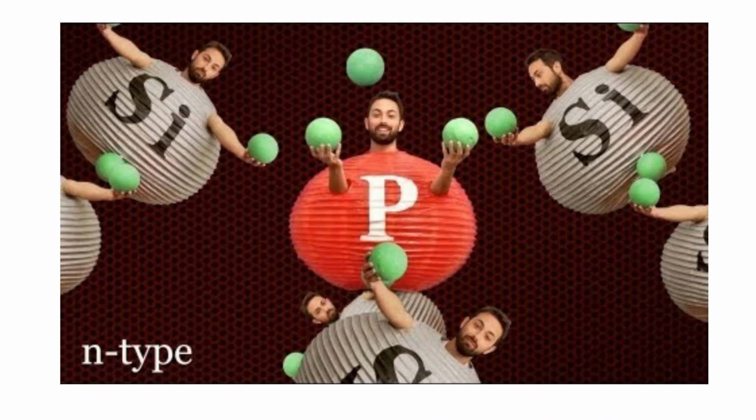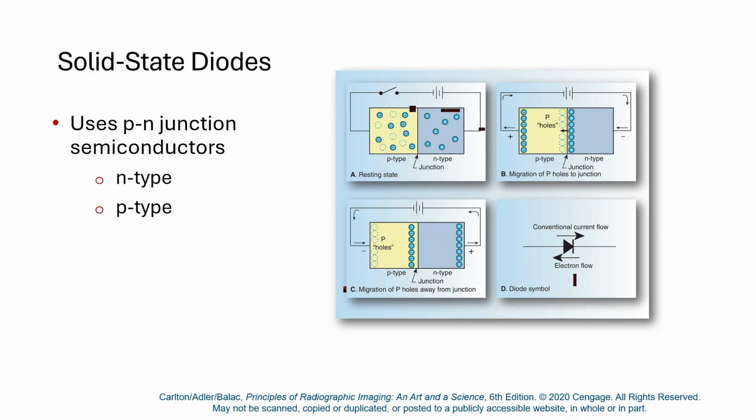All right, so this is our first embedded video. Not going to play that embedded video because it'll mess up this recording. But that is about solid state semiconductor diodes, okay? And so we use semiconductor material in modern diodes. We don't use a point contact diode anymore. It's rather inefficient compared to semiconductors. So semiconductors are doped, that is, we add impurities to the semiconductor.